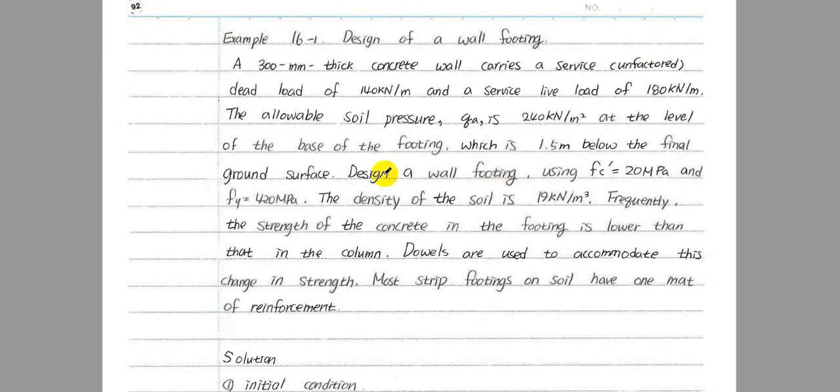Okay, let's talk design of wall footing briefly. This is simpler than the design that we see for square footing because this is a one-way situation. It's like we're designing one-way slabs and the problems are given right there. We have a net bearing pressure over there, and we have concrete strengths and also we have loadings.